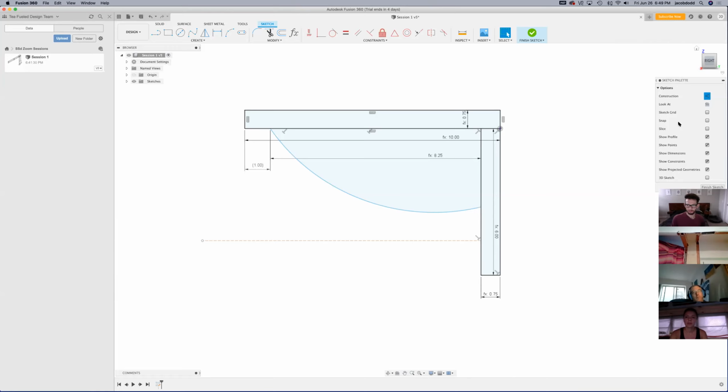I recommend you kind of learn the shortcuts, like almost any software really. It makes it a lot quicker for switching between. So X for construction lines on, X for construction lines off. And I just like to think of that as kind of Xing out the line. Like you can still see it on the sketch, but you would not use that for reference.